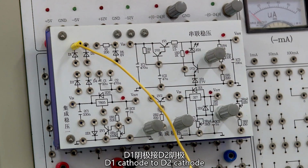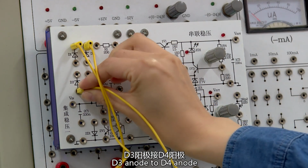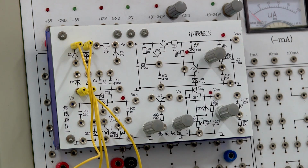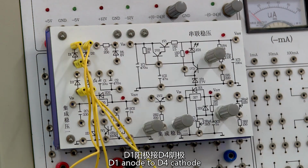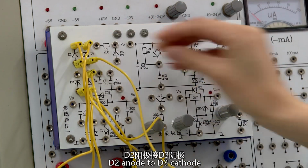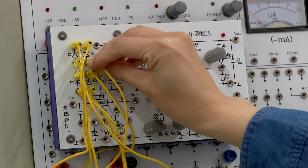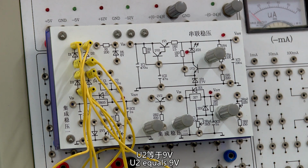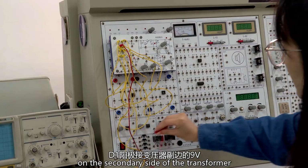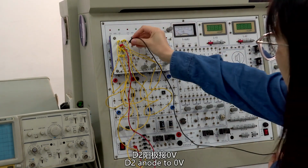D1 cathode to D2 cathode. D3 anode to D4 anode. D1 anode to D4 cathode. D2 anode to D3 cathode. U2 equals 9 volts. D1 anode to the 9 volts on the secondary side of the transformer. D2 anode to 0 volts.